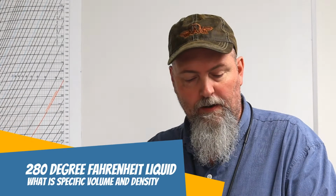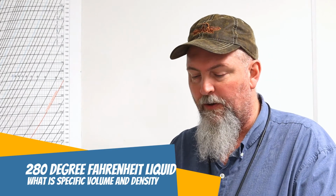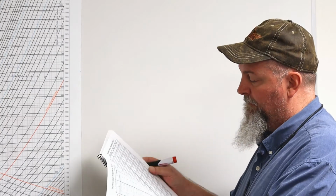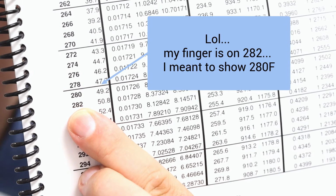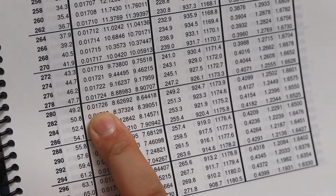Alright, so another question I saw some people struggling with is if I gave you some amount of saturated liquid at 280 degrees Fahrenheit. So you have the temperature. We're going to open up our steam tables to the saturated steam temperature, table 1, and we're going to find 280 degrees Fahrenheit. 280 degrees Fahrenheit gives us a saturation pressure of 49.2 psia and a specific volume of 0.01726 cubic feet per pound mass.